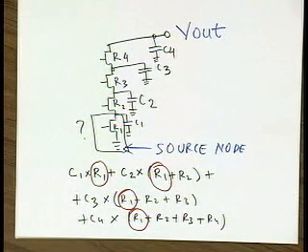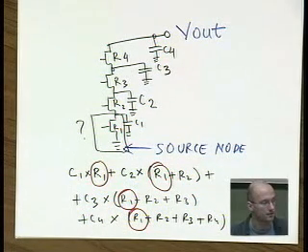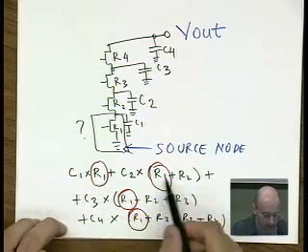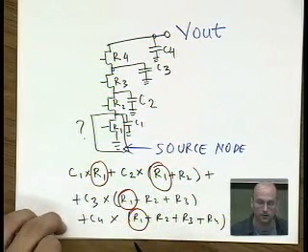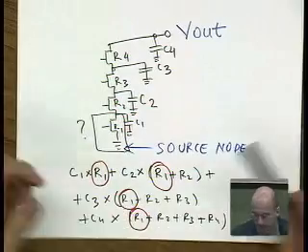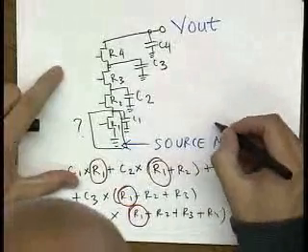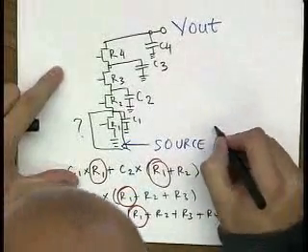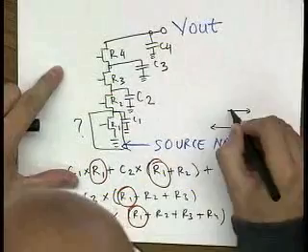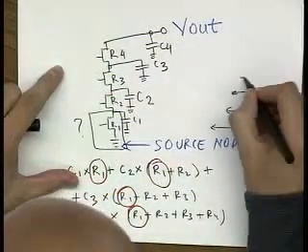Correct, because when you increase the size, you reduce the equivalent pull-down resistance. And that helps you a lot because this R is all over the place, right? And that's actually what people are doing. When you have a stack of devices, the sizes will go something like this. This one will be very wide, this one a little bit narrower, and so on.